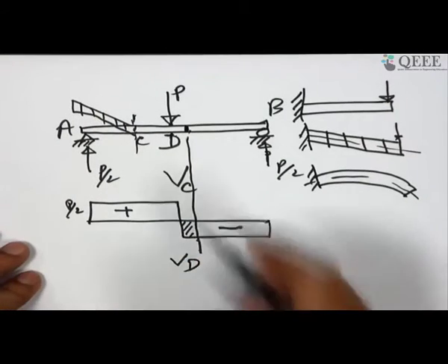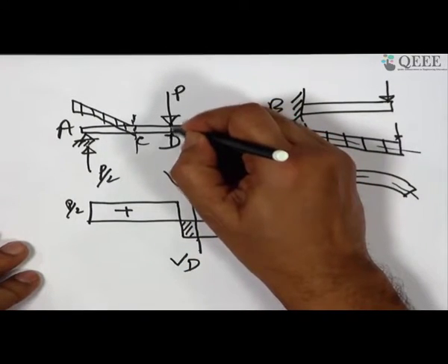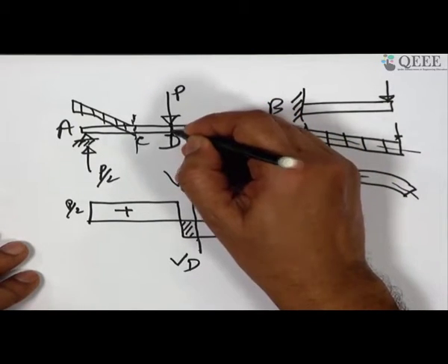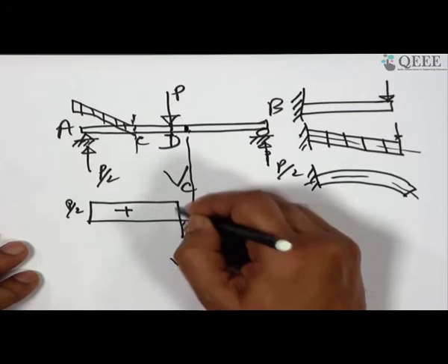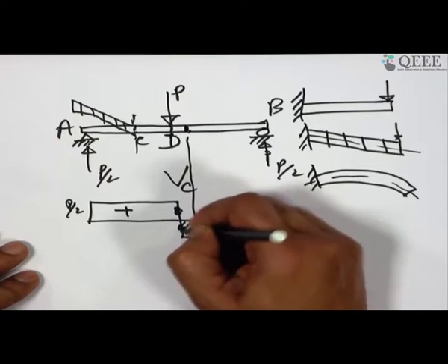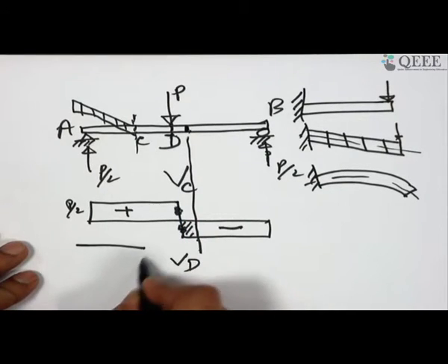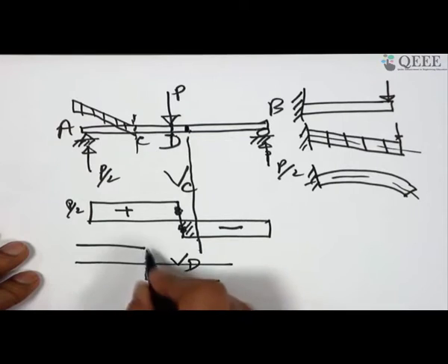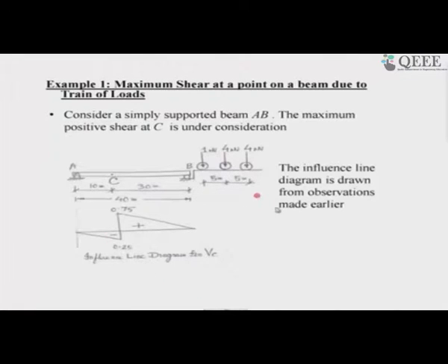So, now the question is, what is the exact shear at D? You have to understand, you do not discuss it, it jumps from one point to another, and we should not join it by this line. We should say that the shear up to here is this, and the shear up to here is this, and we do not discuss what exactly is happening at this point. Our loads, when moving from right to left, I have to examine carefully.